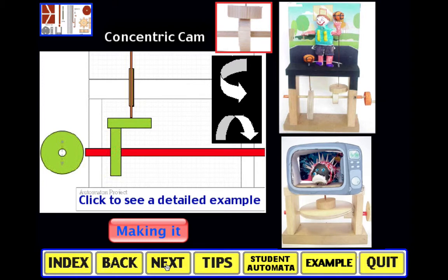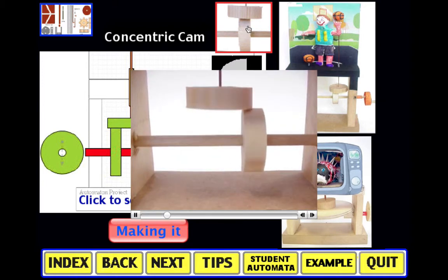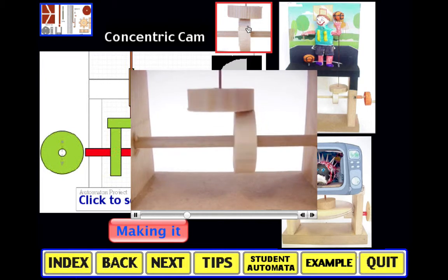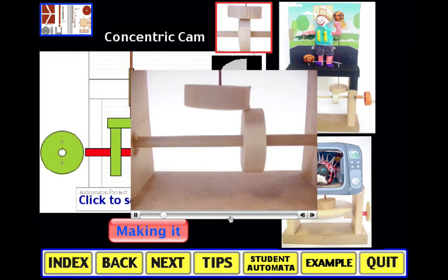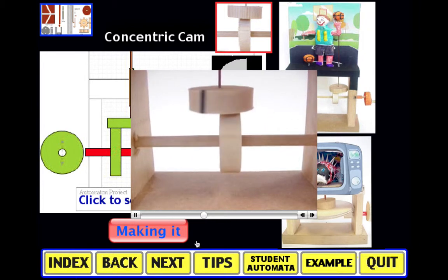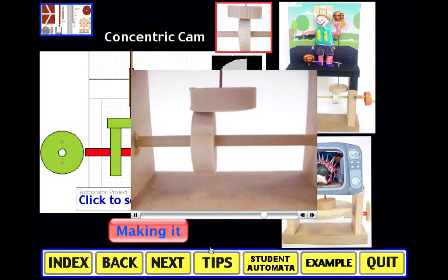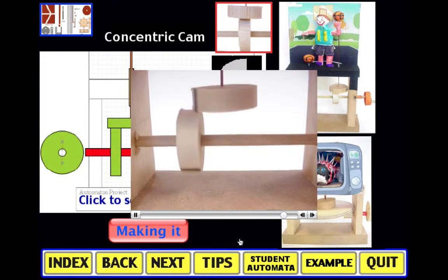This concentric cam shows how rotary movement is moved around 90 degrees, and also how ratio changes and also direction. The position of the cam follow disc over the cam will determine its ratio from the outside 1 to 1, going over to 2 to 1, and then in the middle it will not turn it. Then as you go to the left it changes direction, then it goes back to 1 to 1.